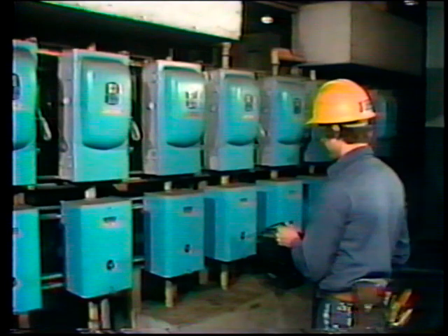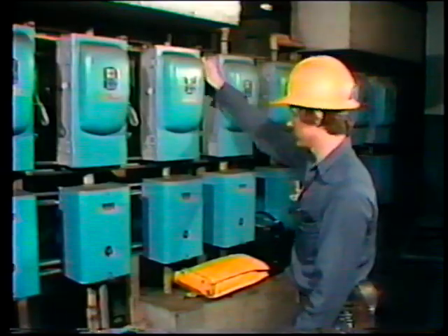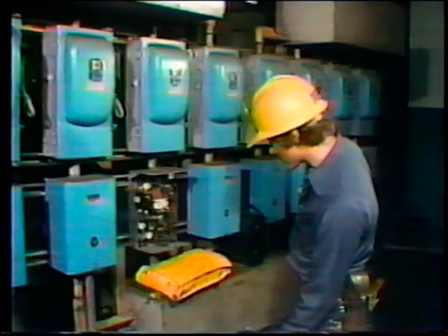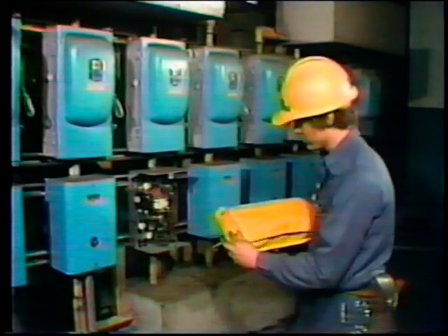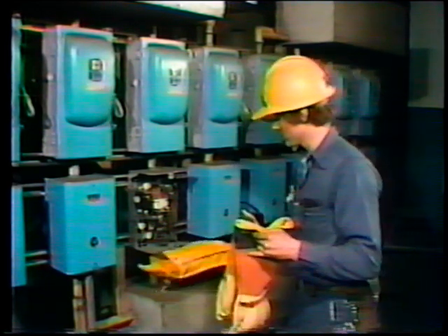Now, since the electrician was unable to narrow down the possible causes of the controller malfunction, he first checks the obvious possibilities. Such components as the power supply breaker, the overloads, loose or broken wires are easy to check and eliminate as possible causes of the problem. First, the electrician checks that the power supply breaker is closed, enabling power to flow through the controller. Then he checks the overload device by pushing the reset button. From experience, the electrician can tell that the overload contacts are closed. The overloads are not the cause of the controller problem.